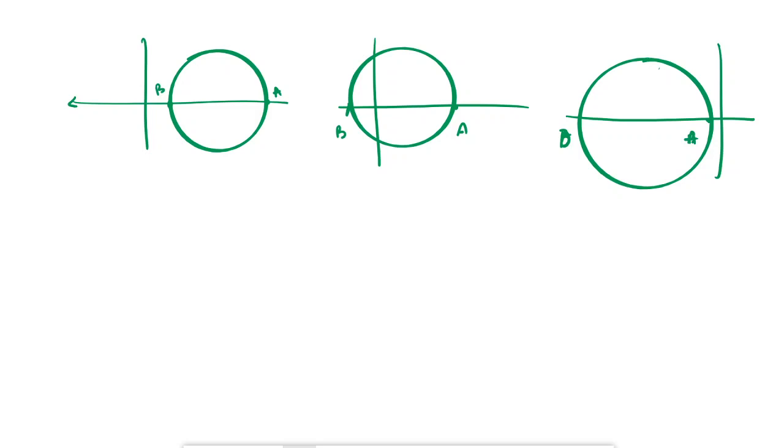If I'm doing MSS, which is just comparing tau max to half of SY, which is what we're calling SSY, the shearing yield strength. You know that this is in reality a 3D Mohr circle.